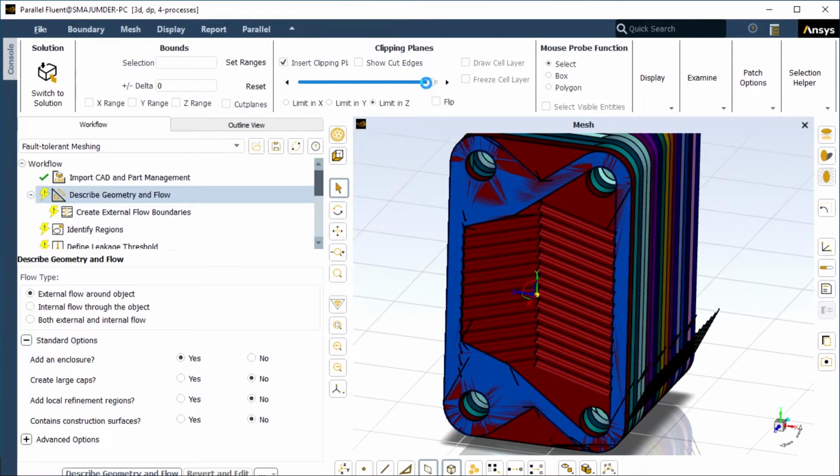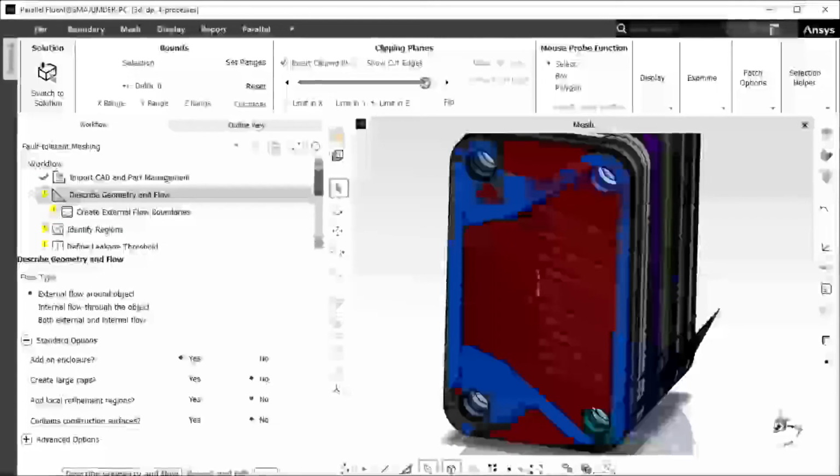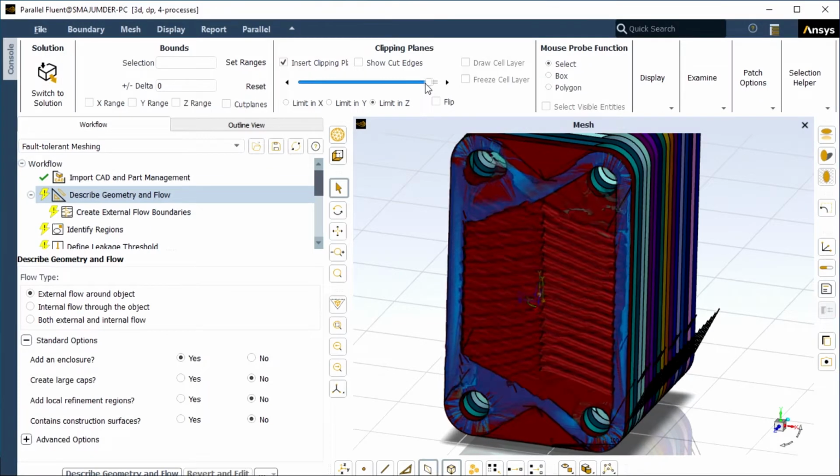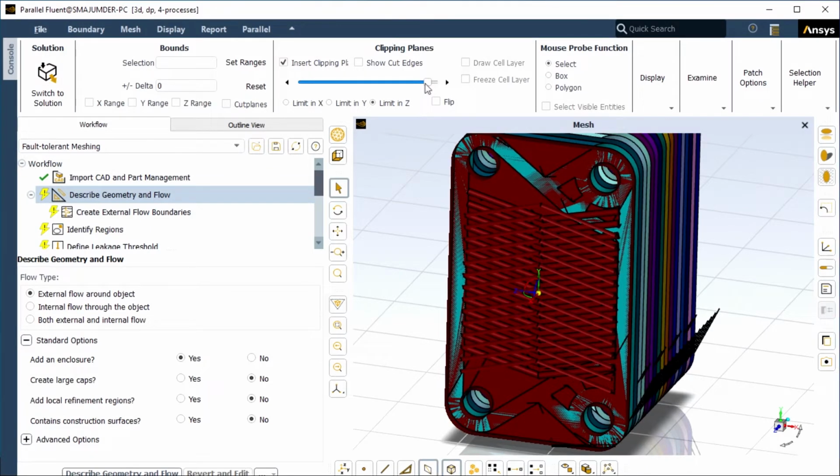You see, in the next plate, cold water will pass from this bottom entry, and at the same time it will move in the forward direction. On the right side there is this bone type of structure. Following it, the water will move to the right hand side, and the right hand side is again closed, right? So there is no direct mixing of hot and cold fluid here itself. Cold water moves from the bottom entry in the forward direction, and at the same time moves to the right following these bone type of structures.